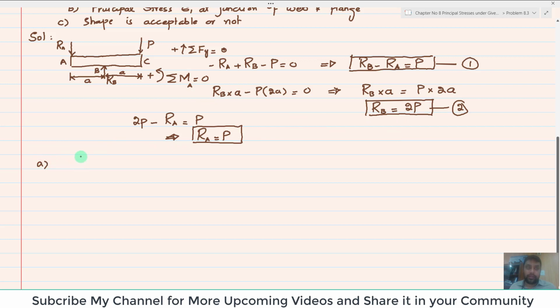In part A, it was given to find the maximum stress in the beam, and we know that maximum stress in the beam is equal to maximum bending moment divided by section modulus. So for maximum bending moment, we will draw the shear force and bending moment diagram of this beam. Let me draw it.